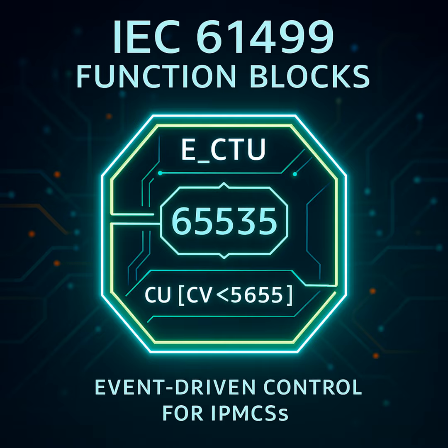Makes sense. And the second is R, the reset event input. Pretty self-explanatory, that one resets the counter back to 0. Okay, CU to count, R to reset. But in distributed systems, feedback is critical, right? If some other block on the network sends a CU event, how does it know the ECTU actually did it? Good point. You need confirmation. So there are corresponding event outputs.